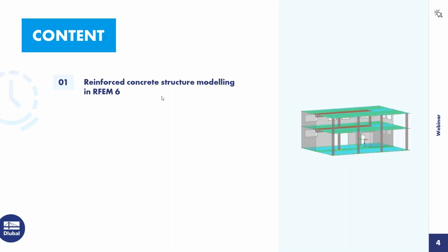So I will present today the modeling and the definition of some additional tools for the design of this reinforced concrete structure. I will especially take care about design of the slab over the ground floor. I will define some additional settings for the finite element mesh generation, take care about the singularities to avoid them, and the joint of the column to the slab.